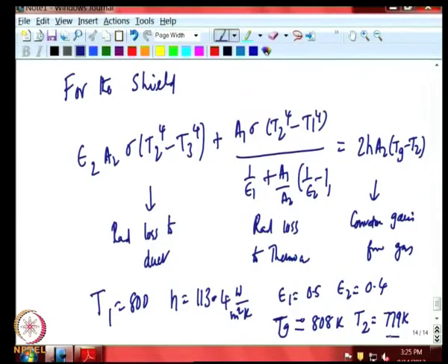The shield already had a high temperature. So, radiative loss of the thermocouple to shield became small. So, the temperature of the shield went closer to the gas temperature. So, now you can see there is only around 8 Kelvin error, which is equivalent to 1%.